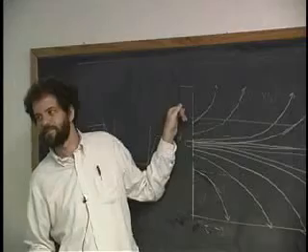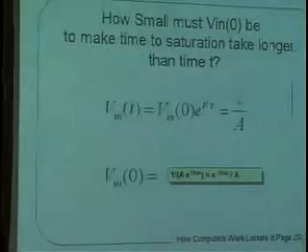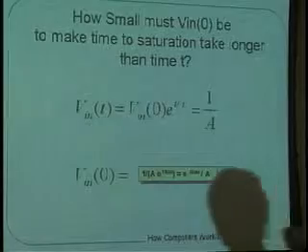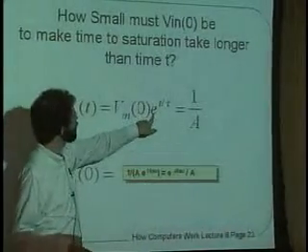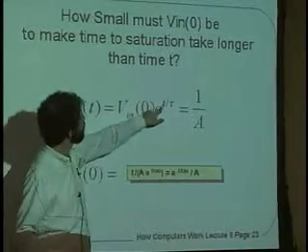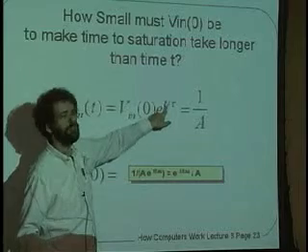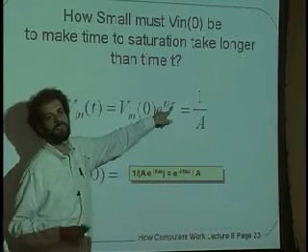Okay, all right. So in fact, what we have, I've just showed you this one, is a function that looks like this. We have an exponent of the constant e, which is 2.71828, times t over tau. Now t is time, and tau is what's called the time constant of the circuit.